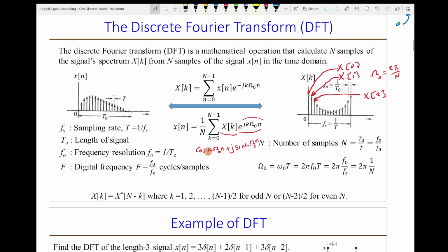So the sum of all these complex numbers, where j, or in some textbooks I, is just the square root of -1, has to cancel all the j, so you end up with a real signal, x of n, because this is a real signal. It doesn't have complex values. Well, this will dictate the following. Let me clean up first. That first point here is the DC, the strength of the DC component.